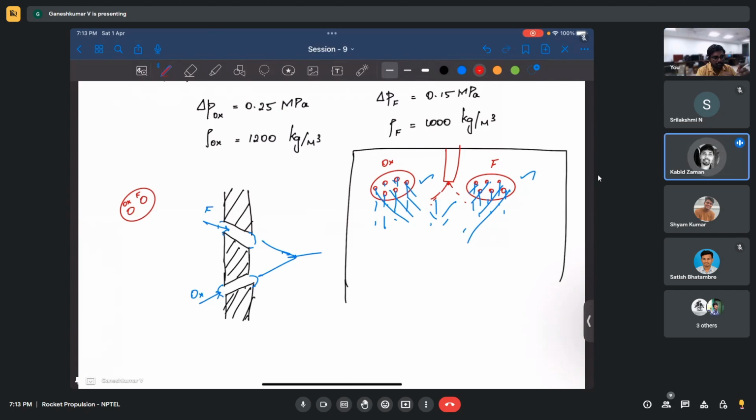No, actually, what I was asking is, compared to solid propellant rockets, do we need more ignition energy in the case of liquid, or less? Liquid should have less, I guess, but I'm not sure about that. That is what I'm asking. In the case of solid rockets, we sometimes need a smaller igniter to ignite a larger igniter, and then that igniter ignites an even larger one, and finally the SRB catches fire. Right. But what about liquids? Do we need some sort of cascade, or is a small igniter more than sufficient?